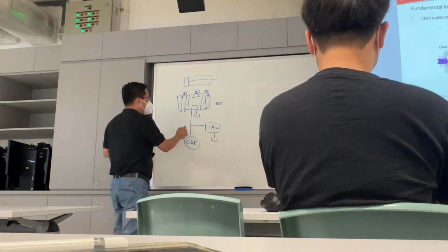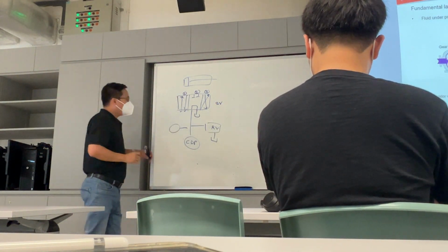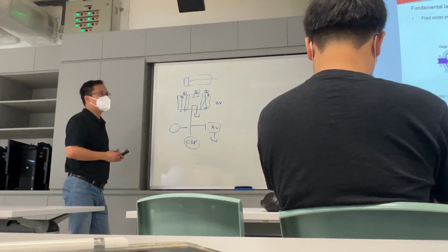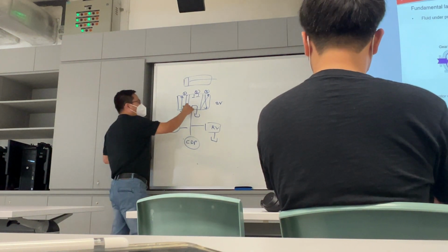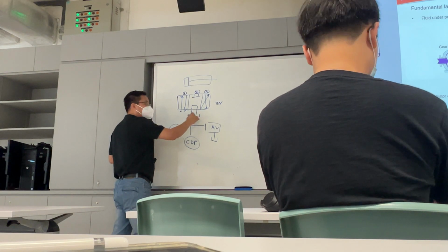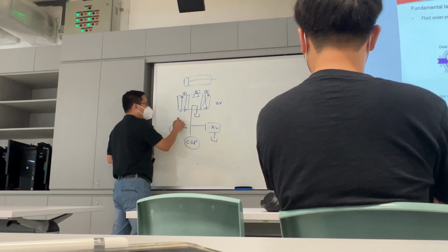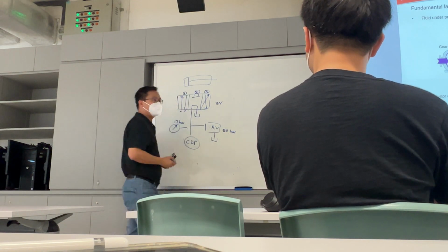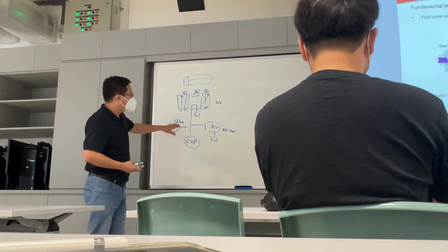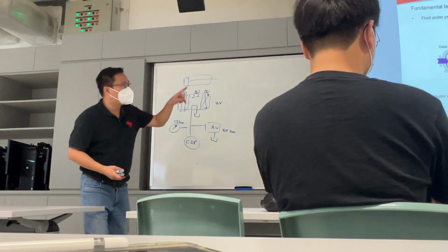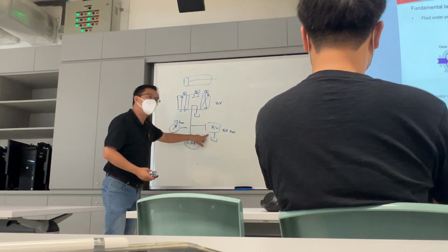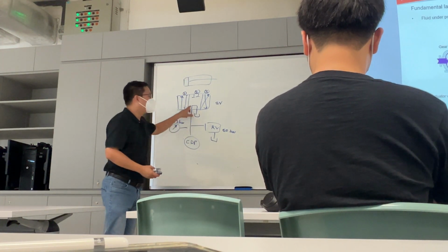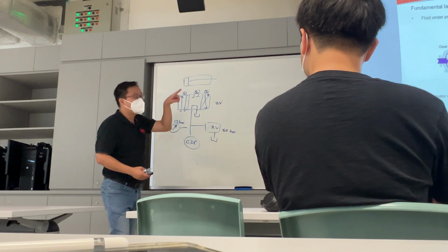Now, if you remember your experiment, when we switch on the constant displacement pump, what happened? The flow went out immediately. So the gauge shows how much? 12 bar. And you set the relief as 50 bar. Alright? Now, when it goes up from here at 12 bar, it tells you that it did not go through the relief valve because this one is an easier path. So that's why this resistance.